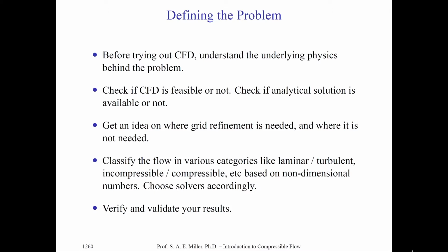You'll have to get an idea of where the grid must be refined, that is, where we're placing grid points. Remember, we only know solutions where we have particular grid points. That's where the computer solves the problem, and of course, where it's not needed. The more grid points you add, the larger and faster a computer you'll need to solve it in a reasonable time. Every grid point takes memory and processor to assess.